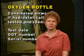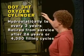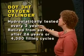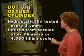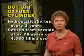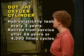Now, in addition to standard bottles, there are also lightweight cylinders, known as a DOT 3HT oxygen cylinder. They get less time between hydrostatic testing. They have to be hydrostatically tested every 3 years instead of every 5. And on the lightweight cylinders, they have to be retired from service after 24 years or after 4,380 filling cycles, whichever occurs first. So they get a long life, 24 years, but they don't get an awful lot of filling cycles, only 4,380.